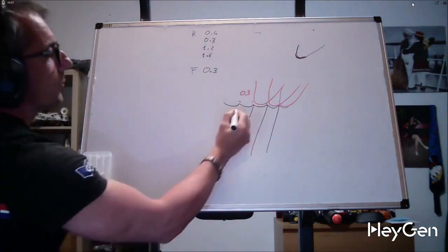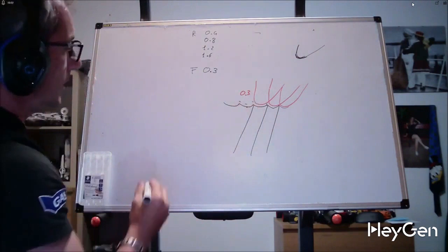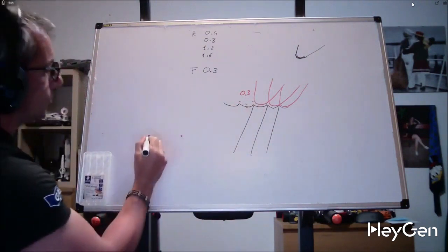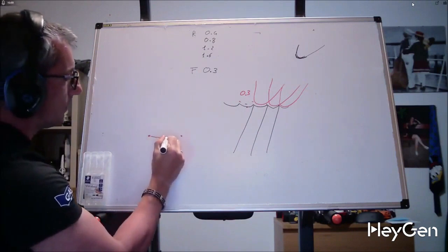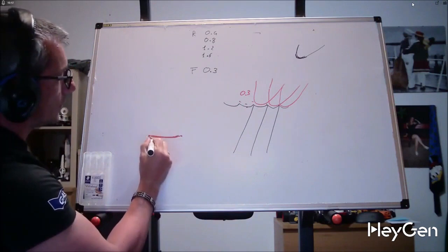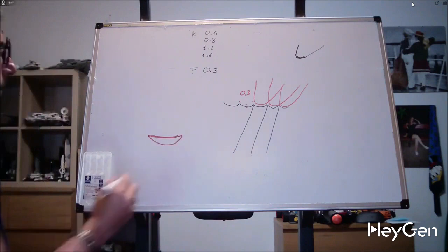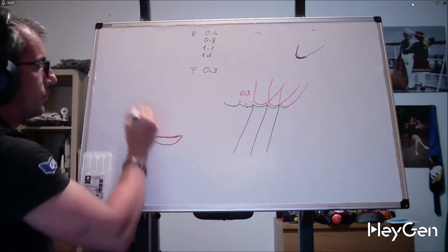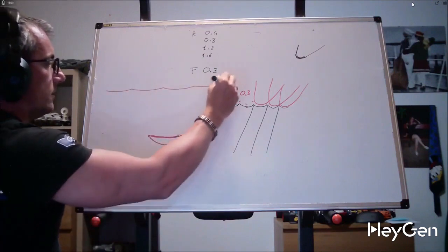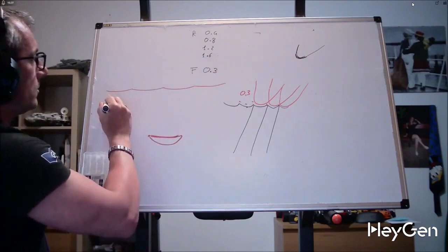You will understand that the depth from here to here, if I use a radius of 1.6, my groove will look like this, just slightly pronounced. If I used a radius of 0.4, my groove will be like this. So, the first radius is 1.6. With approximately the same feed of 0.3, radius 0.4.